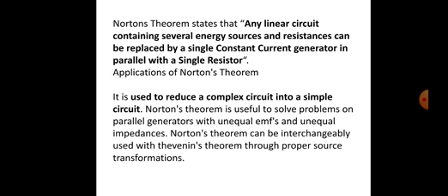The Norton equivalent circuit. Norton's theorem states that all linear circuits can be simplified to an equivalent circuit with a single current source in parallel with a single resistor connected to a load. Step 1. Remove the load resistor and replace it with a short circuit. Step 2. Calculate the Norton current, the current through the short circuit.